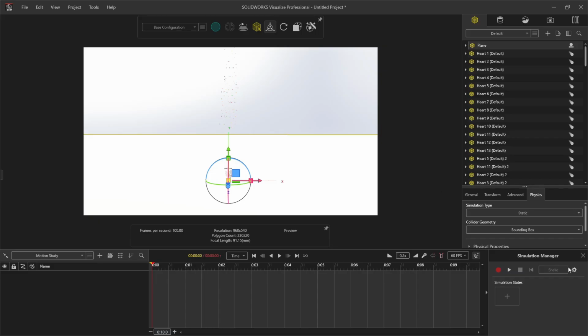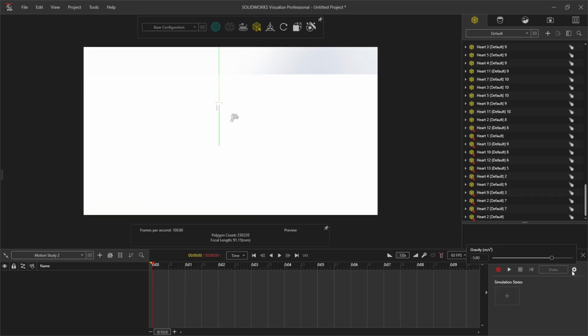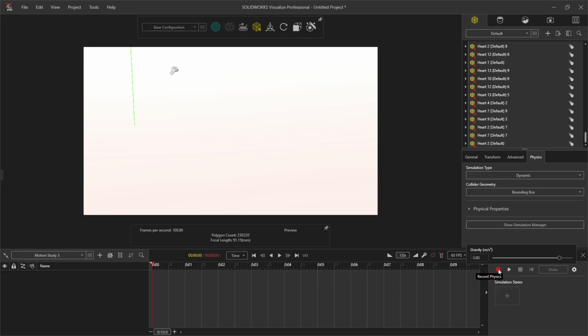The next step to look at is the cog icon, which is the gravity settings for the simulation. Right now I have the gravity on 3 meters per second. The Earth's gravity is 9.8, but I use a much lower level of gravity to slow down the fall speed and allow myself the ability to create more render frames from the animation. I can then record the simulation.